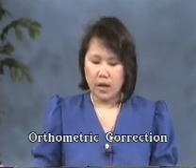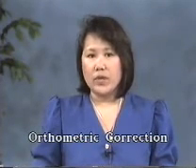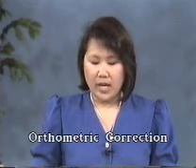And last, orthometric correction. Because the Earth is not a perfect sphere, the effects of gravity and centrifugal force vary somewhat at higher elevations. This variation must be corrected on long level runs, made in a generally north-south direction at higher elevations. A discussion of this correction is given in Chapter 5 of the Caltrans Manual.